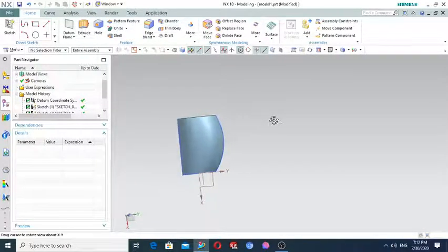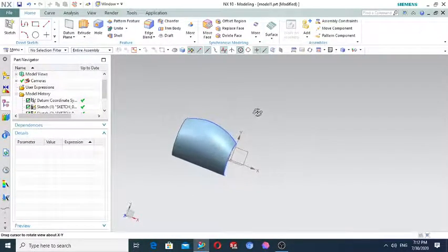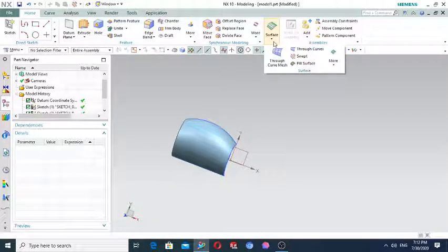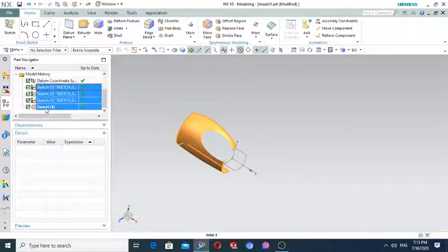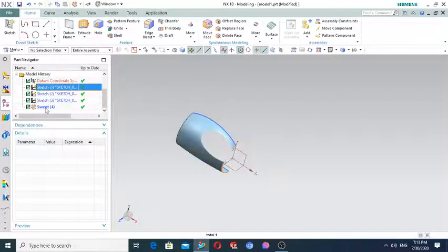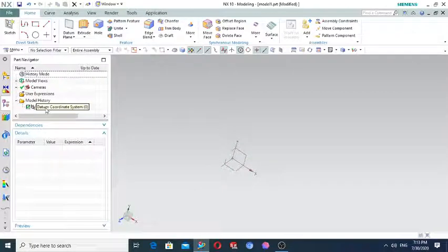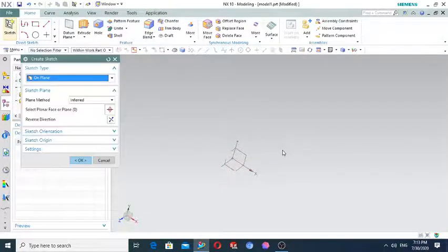So this is how to obtain such kind of curve using the swept, and mostly you can obtain caps and some bottles using the swept function. Anyway, you can obtain the caps and the bottles using all of these three methods. They just have different ways of obtaining the same object. Let's see briefly how to make, for example, the bottle using the swept function. Delete, for example, the sketch.